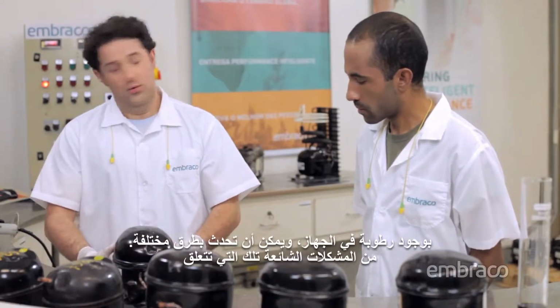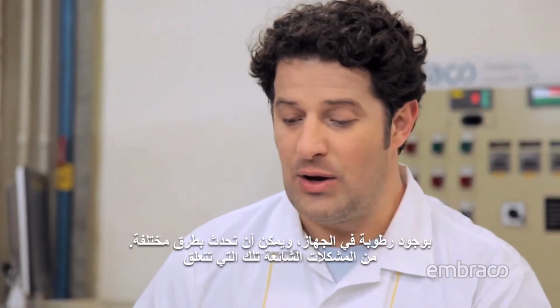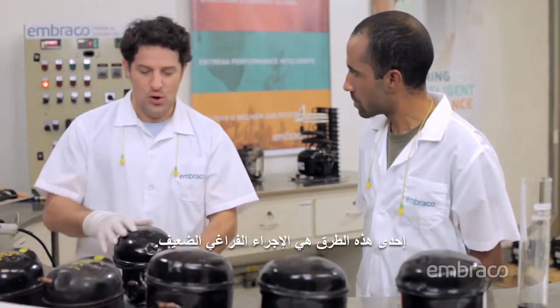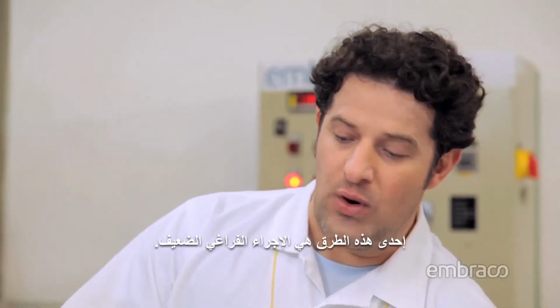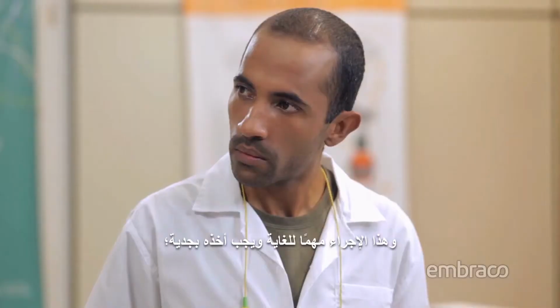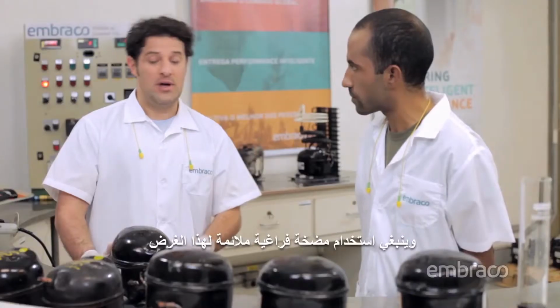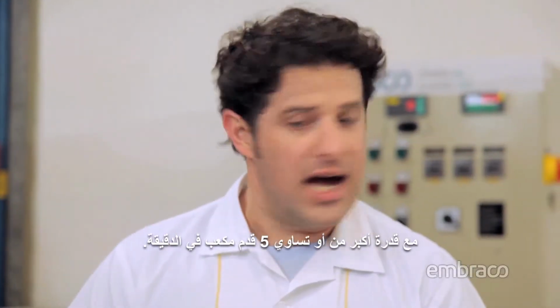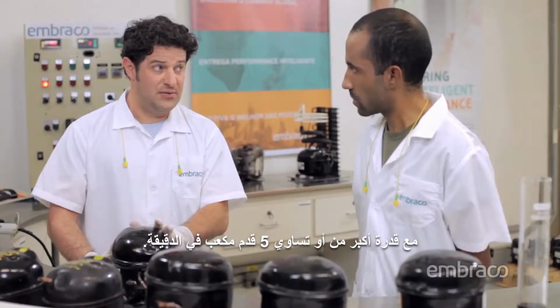One of the common problems is related to the presence of moisture in the system, which can occur in various ways. One of them is through a poorly done vacuum process. This process is extremely important and must be taken seriously. A vacuum pump suitable for this purpose must be used, with capacity greater than or equal to 5 CFM.